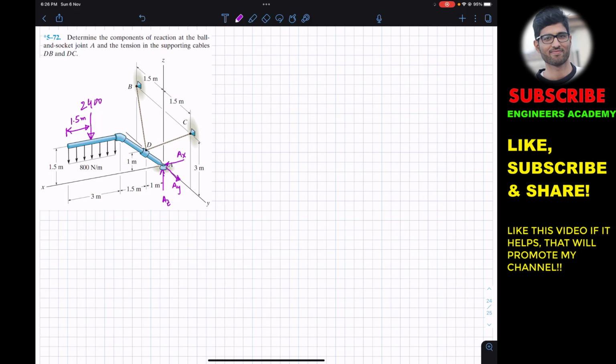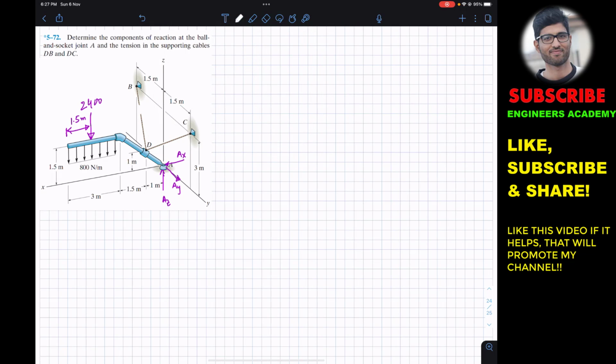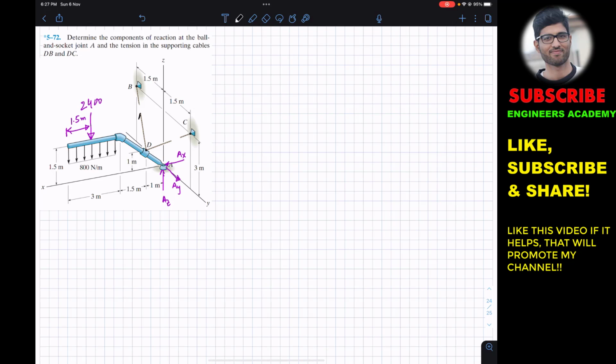Now, since the problem statement says we are required to find AX, AY and AZ and the tension in both of these ropes, for that we have to cut these ropes. So let me cut this rope somewhere here, and let's say that the tension in this DB cable is T1, and this one is T2.